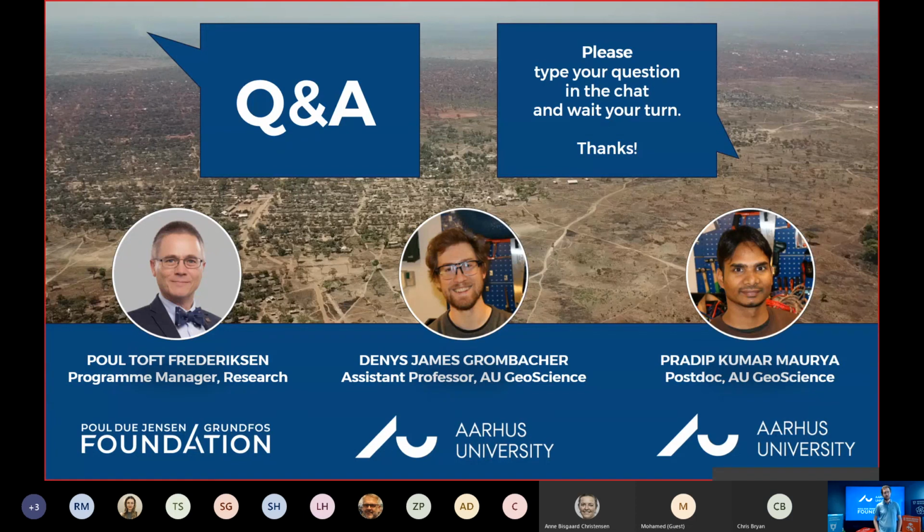What accuracy tolerance does the system have? Asks Amit. Yeah, that's a great question. Your ability to differentiate between different geological units depends on there being an electrical contrast between the two. So if you had two different geological units with the same electrical properties, as far as the TEM system is concerned, it would image a single unit.